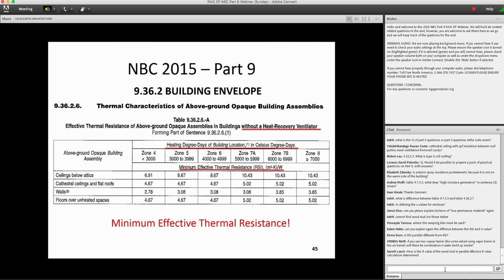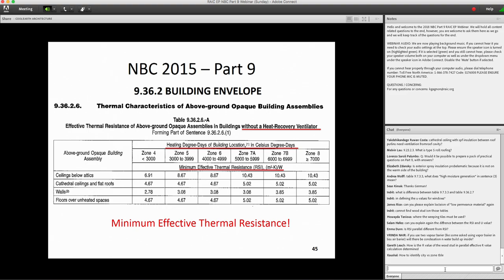Location of the zone table. I'm back. Again, it's in Division B, Appendix C. It starts on C11, and you have different provinces. There's a column called degree days below 18 degrees centigrade. That's the number that you have to compare. Okay? Division B, Appendix C.